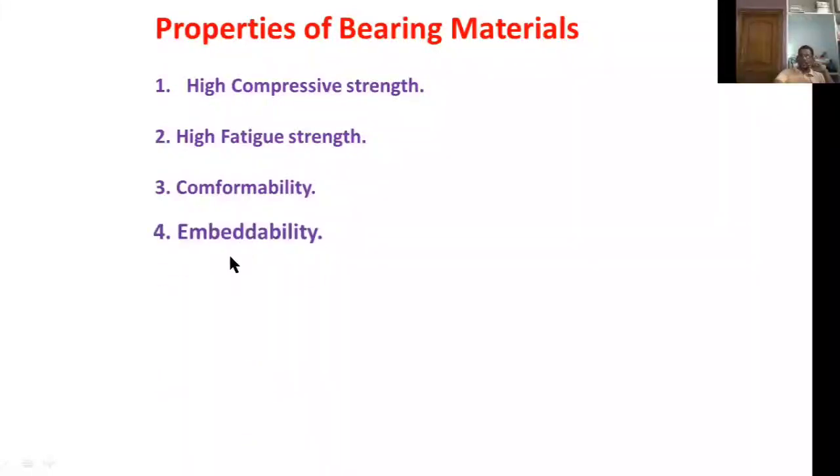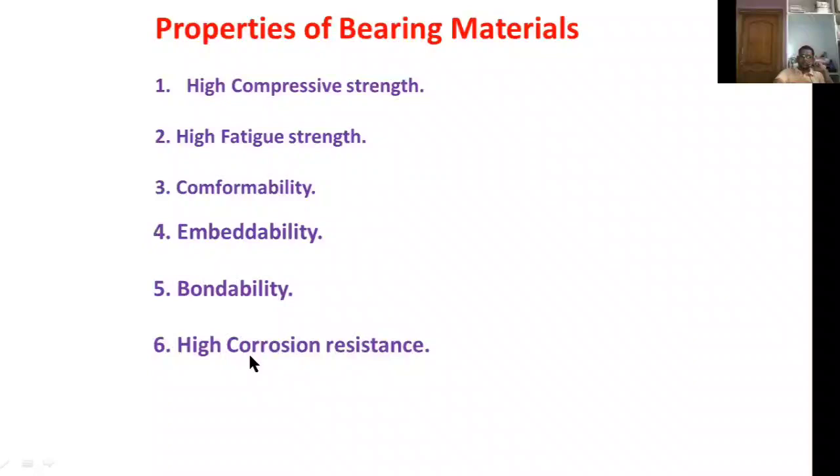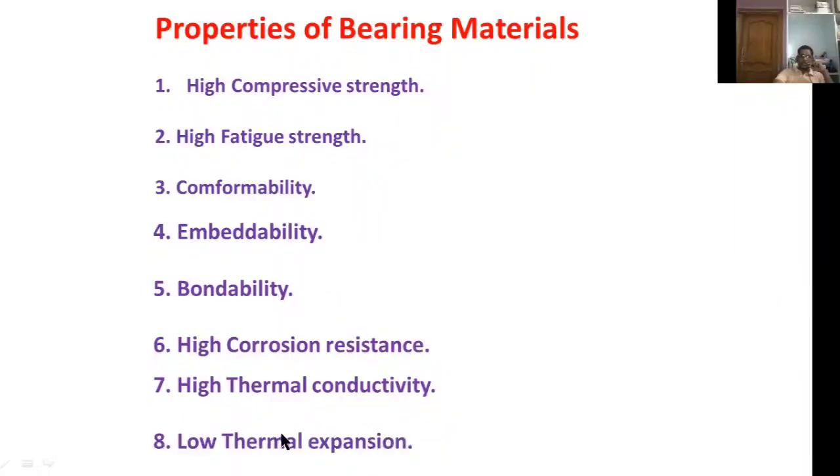It should have embeddability. Okay, bearing metals should have good bondability. Okay, and bearing materials should have high corrosion resistance and wear resistance. Okay, and also the bearing materials should have high thermal conductivity and low thermal expansion.